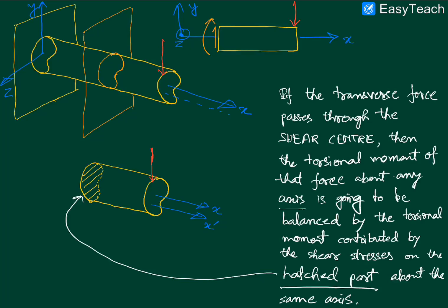So the thickness of the various members which made up those sections was very, very thin. And as long as we have that kind of thin section or thin members making up the cross section, it is possible to find some kind of closed form expressions for the shear stresses, and that is what we are going to concentrate on next.